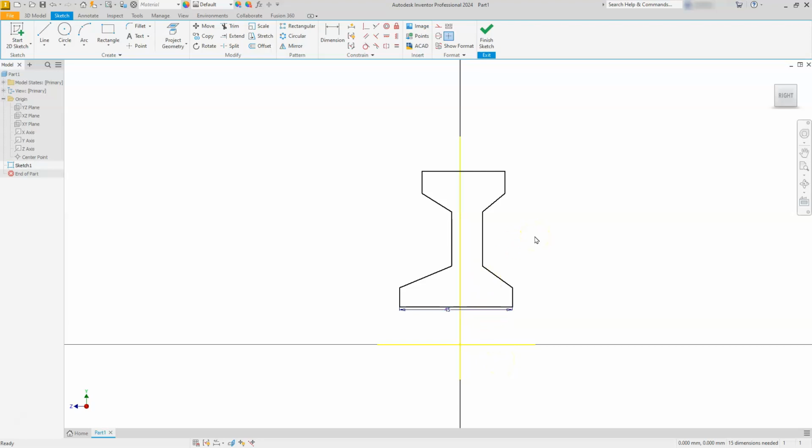All right, so the first thing I'm going to do is make these lines symmetrical to this y-axis. The way we're going to do that is use the symmetrical constraint. Once I select that, I'm going to select this line, and then this line, and then you select the line that you want it symmetric to. So once again, I'm going to select the outside line, this outside line, and since I did not restart the command, it assumes that everything is going to be in line with here.